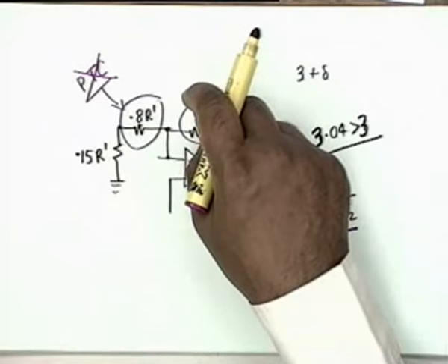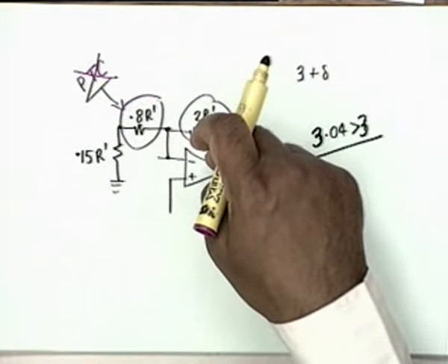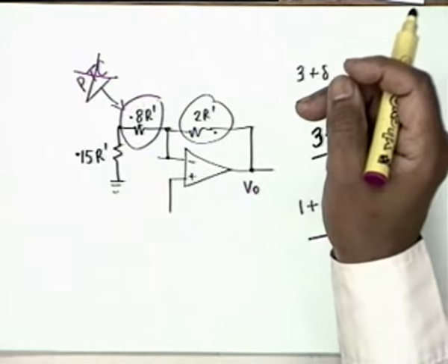In the olden days, when NTCs and PTCs were not readily available, people used to use an ordinary light bulb in place of one of these resistors. Of course, op-amps were not available, they used to make with valves, and therefore valves, VALVES, and therefore BULBS were the natural choices. And obviously electric bulbs are temperature sensitive. Positive or negative?